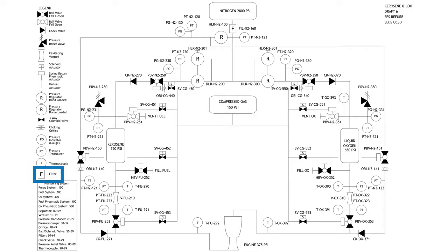So once we get this system cleaned, the entire oxidizer side has to be cleaned off, because oxidizers will make fuel out of anything. I mean, NASA showed us a bunch of videos basically where the valve they had was holding like 75,000 psi. It was absolutely massive. And when it opened up, it was vibrating just a little bit. And that oxygen, when it comes crashing in through that valve, that vibration caused enough friction to ignite that liquid oxygen. And so it made the metal of the valve a fuel itself, and the valve just blew up. And it started melting, and then the engine blew up, and it was total catastrophic.